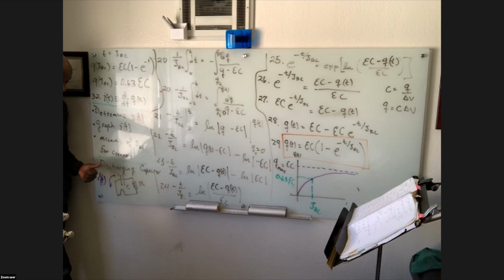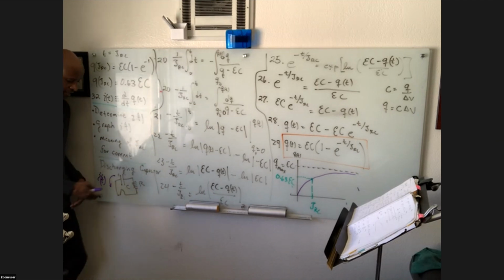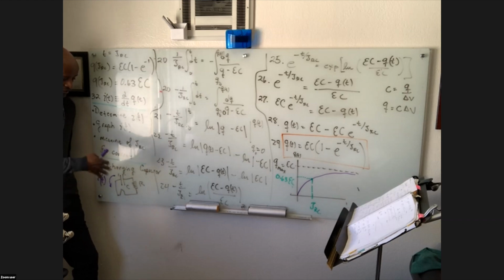The voltage across the capacitor will be a maximum value, but it's time dependent because this resistor is turning electrical energy into heat by Joule heating, which we defined last week or whenever it was. So as the capacitor discharges, the resistor heats up and releases that energy as heat. And so the current will die to zero as the voltage on the capacitor dissipates and as the charge obviously dissipates.